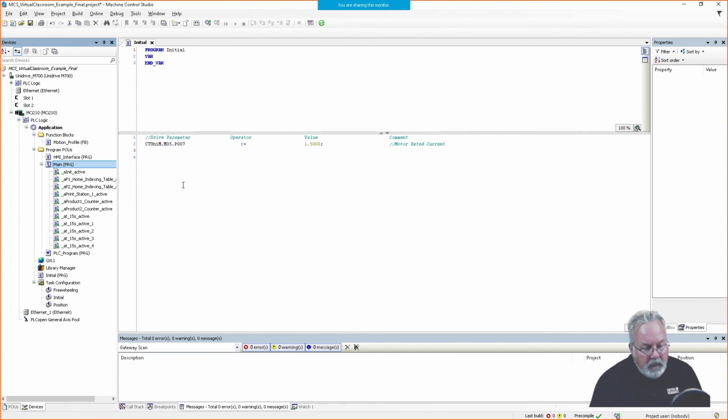The rule is, I would avoid using clock task unless you absolutely have to. When would you ever use a clock task? Well, I would use a clock task if it were important to go out and take a snapshot of motor position, maybe. Or if I wanted to deterministically, every 4 milliseconds, I need to do this. In other words, it's something that has to be executed at a given time. Other than that, I would avoid clock tasks.